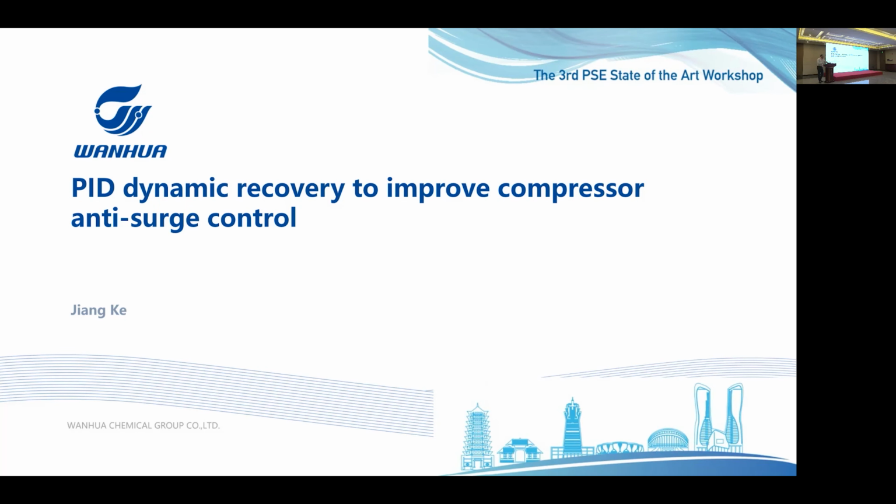Actually, we want to prevent the process value from going beyond the set point. For example, we have a vessel running at a normal pressure of 6 bar, and we have a relief level on this vessel set at 8 bar. In this case, we increasingly like to implement protection control. So we set the set point at 7 bar, for example.